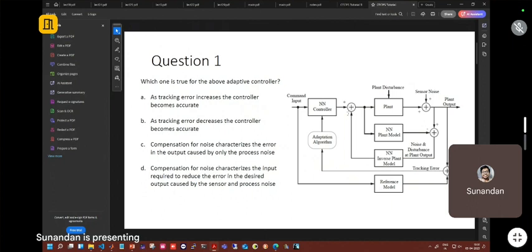So it is adding that to the neural network based controller's control output, and the plant output is also being sent to compute the tracking error. The tracking error is being fed to the neural network controller following an adaptation algorithm. Maybe we are modifying the loss function or updating it some other way, updating the neural network based controller, training it.